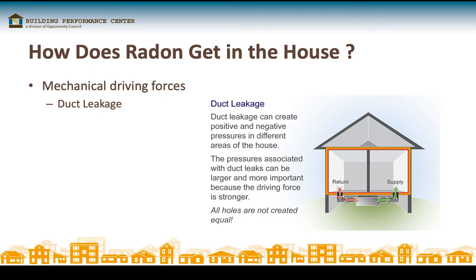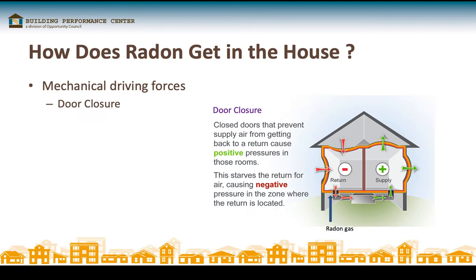You could technically, if you have supply leaks in the crawl space, that's going to pressurize the crawl space, and it would tend to help drive radon gas up into the building, as well as return leaks, which would directly pull it into the building.